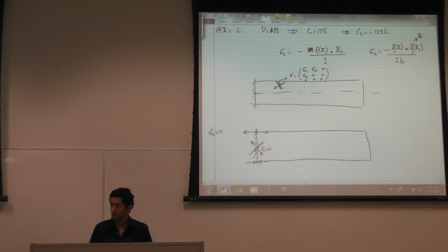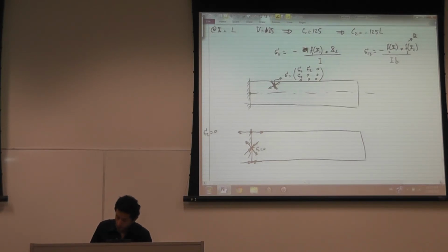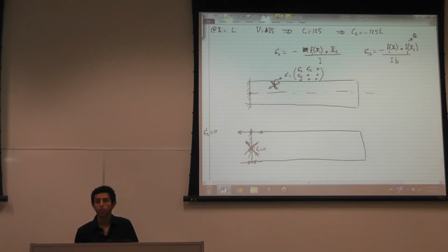And that's why in concrete beams, for those who are civil engineers, you know that closer to the support, because I'm worried for a cantilever beam, I'm worried about what we call shear stress. In fact, what I'm worried about is not the shear stress. What I'm worried about is that tensile principal stress, because the concrete is not good under tension.